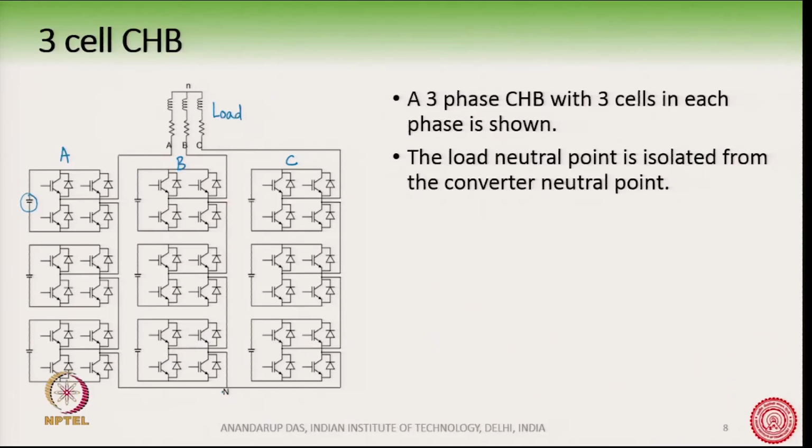This neutral point here is isolated from the neutral point of the load. Usually they are all isolated, and there may exist a potential difference between this point here and this point here, the load neutral point and the converter neutral point.